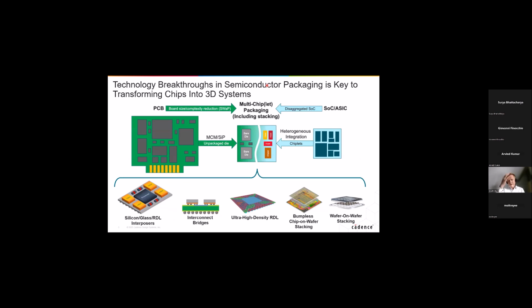Looking at the history, packaging was mostly driven by PCB type technologies, but over time additional technologies have come into play, like silicon interposers, interconnect bridges, wafer level, high density RDL type packages, and even stacking of chips on wafer or wafer on wafer.